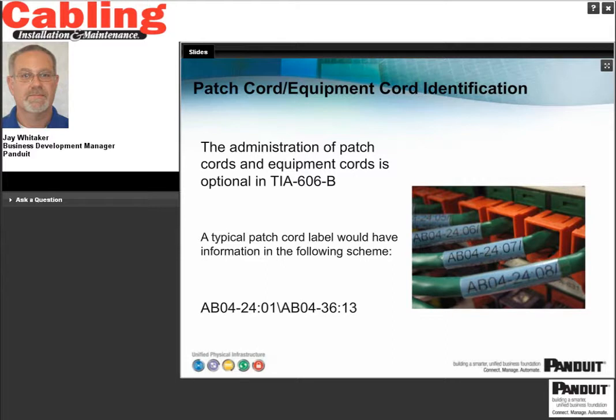So the building cabling subsystem 2 and subsystem 3 backbone cabling identifiers are very similar to what you might have in a subsystem 1 cable identifier. You've got a to and from. Again, you're going to want to have the port that's closest to the NDA listed first in the identifier. So the identification scheme for a backbone cable indicates the to-from routing of the cable within that building. The near-end port identifier and the far-end port identifier are used with a / between the two locations. The port that's located closest to the NDA in the cabling topology should be listed first, and the cable should also be labeled on both ends.